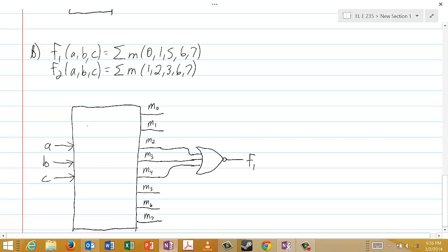Now, clearly, if that claim is true, that's better than our previous option of having a 5 input OR gate, because remember, again, we're supposed to minimize the total number of inputs, and this NOR gate just has 3 inputs. So this is preferable if it is correct, but the question is whether or not this is correct.